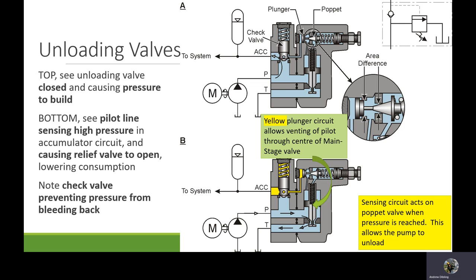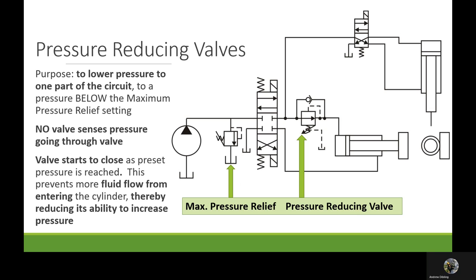So this is an isolating device here. Now the difference here is you'll see that you have a nice flat disc on this side and you have a poppet cone on this side. This presents a lot less surface area than this does. And with the same force, of course, this will help push it closed. If pressure comes this way, it will open it up, right? So the sensing circuit having the two different surface areas allows that to happen.